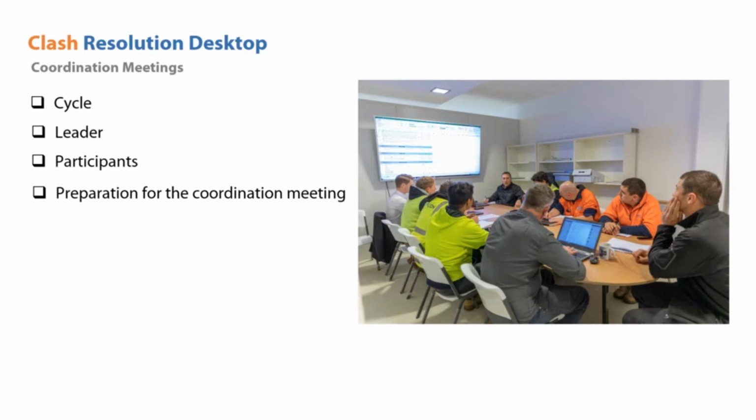One important thing is verifying, in Navisworks, that the 3D views that will be presented during the coordination meeting are clear enough for all participants to understand the issue. And the last part is that all the decisions made during the coordination meeting can be documented directly in Navisworks by adding a comment to the clash and the actions assigned. This is one specific option available inside Navisworks Manage to make the model archive.